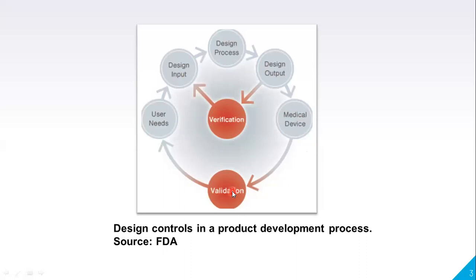Clear? Yes, sir. So in which step is verification applied, and in which step is validation applied? Manufacturing means whether giving the input design, the design process or the design output, verification can be carried out. After completion of the manufacturing, that is the medical device, validation must be done in order to check whether the completed device reaches the defined standards or the user needs.